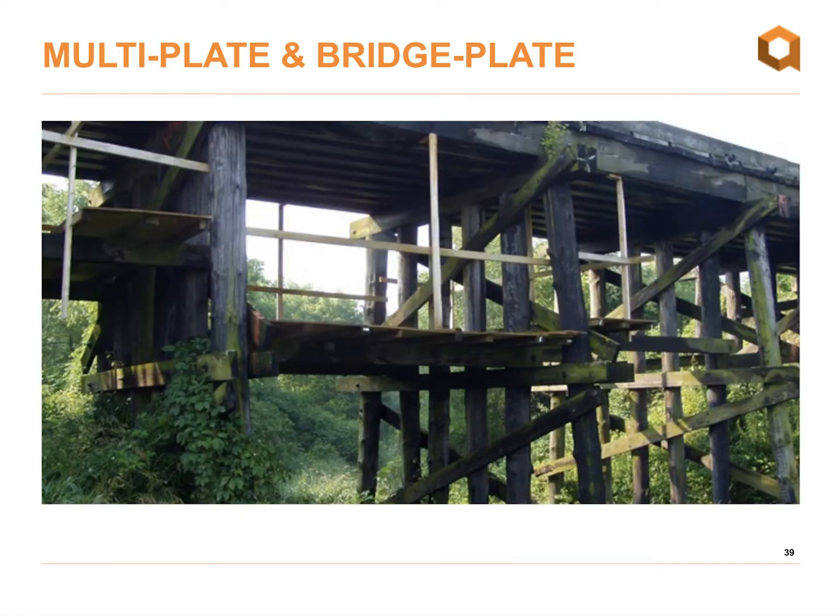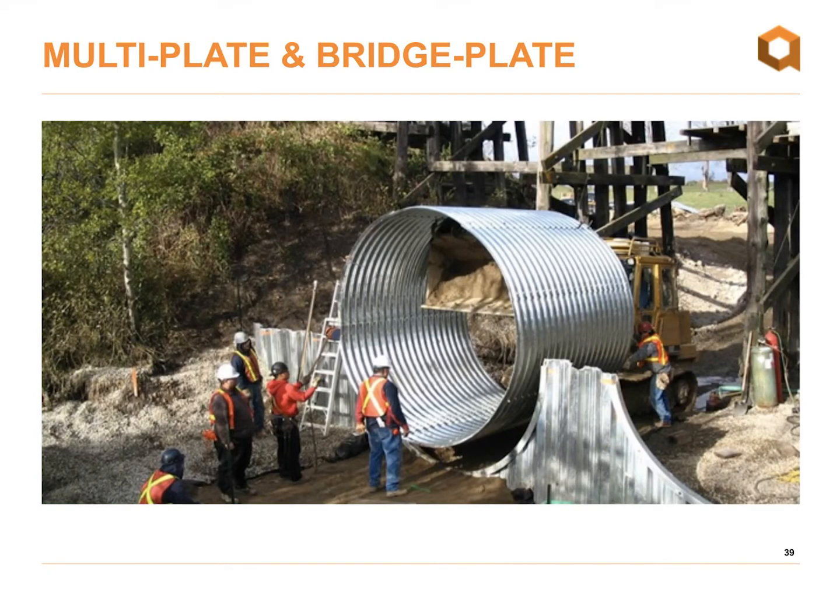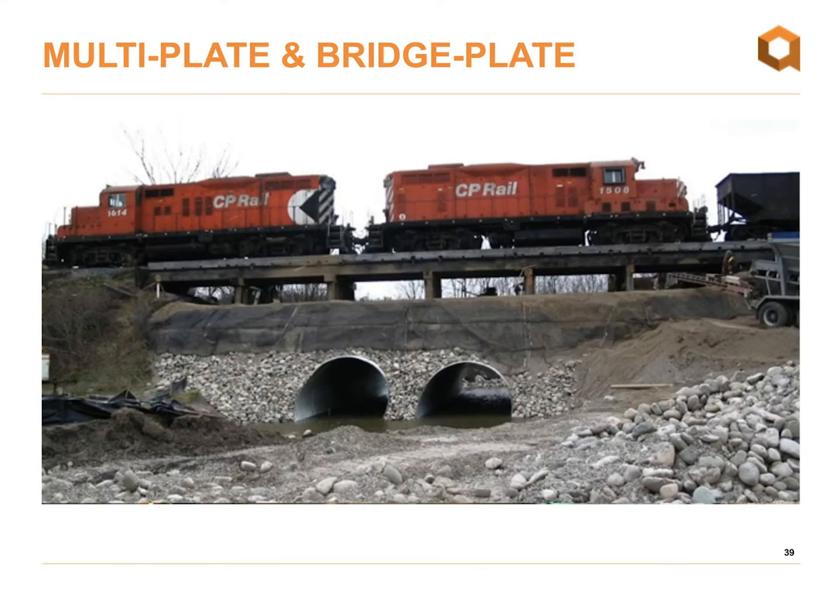So this slide is just highlighting the wide breadth of applications where we've used multi-plate and bridge plate in rehabilitation scenarios. This is an old wooden trestle bridge in Ontario, I believe owned by CN Rail. We were able to rehabilitate this structure with twin multi-plate rounds, I believe about 4 meters in diameter. So a fairly simple installation, a fairly simple rehabilitation process.